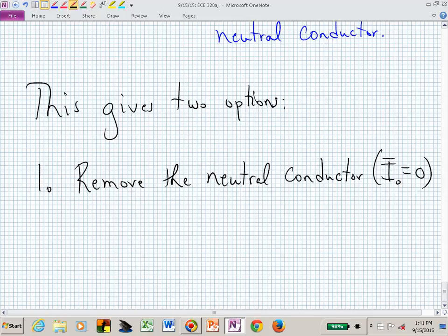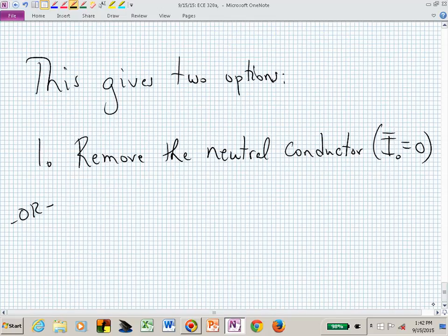That's with a balanced system, and we have what? This sum of I sub AA, I sub BB, and I sub CC all flowing through that conductor. And since it's balanced, they all sum to 0. In a real system, that might be why the neutral is there.